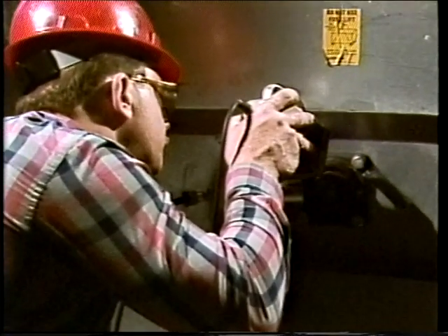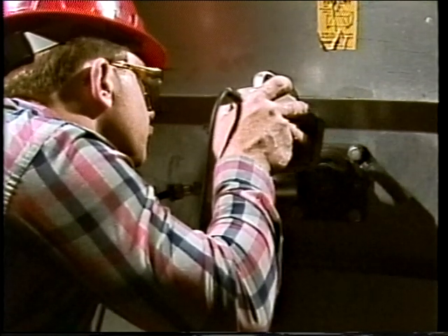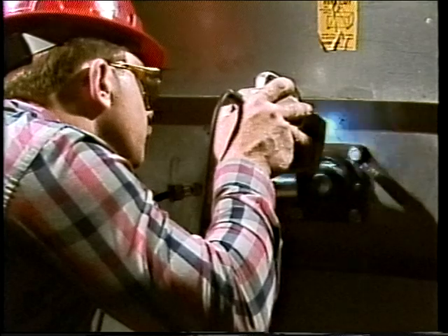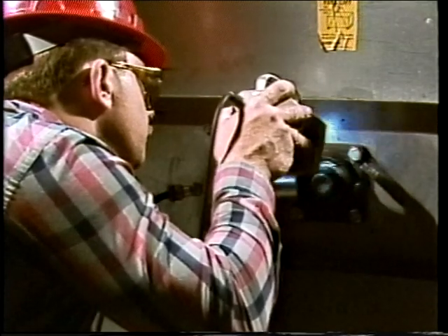The machine can also appear stationary if the strobe flashes at a frequency equal to a fraction of the machine's speed, or a whole multiple of the machine's speed. You'll find some additional information about how strobe lights can be used to determine a machine's speed in your text.